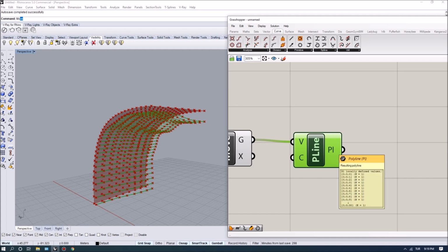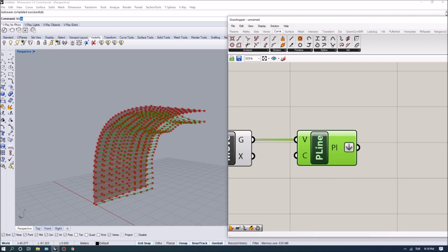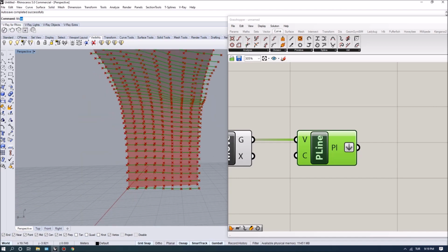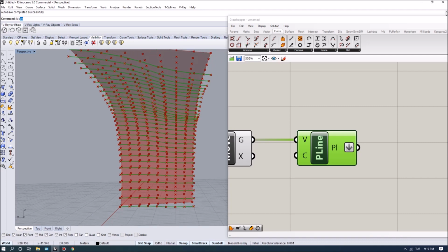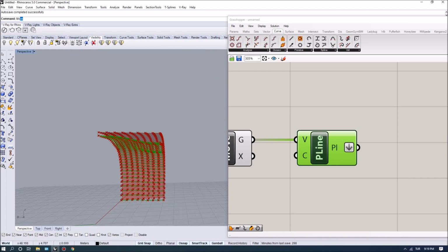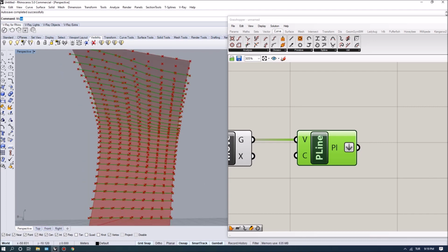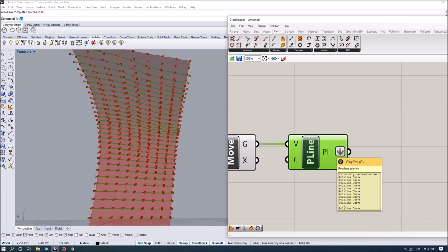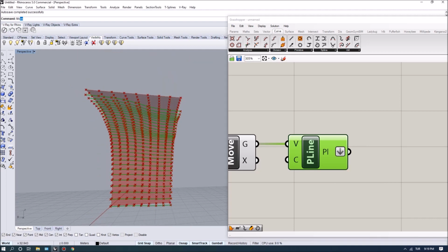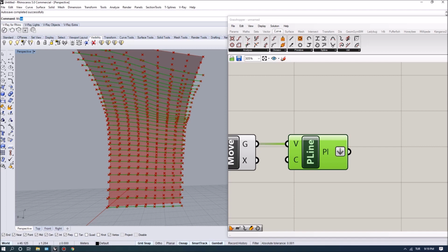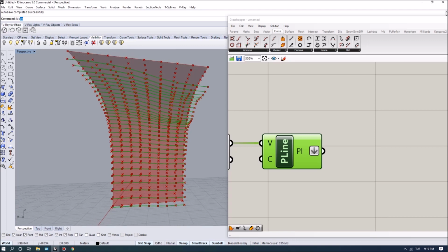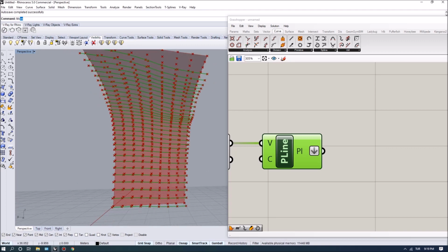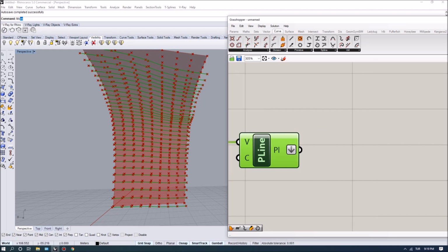And I want to simply flatten this list out so that we can work with it. So what I want to do next is connect each of these rows using triangles. So this line will be connected to this line by building triangles. And to do that, we first start with the initial list. So we have 31 curves. And since I'm going to connect each curve to the next one, what I want to do is create two sets of lists using the shift list command, so that we can transpose the list to connect or relate each line with the next line in the list.